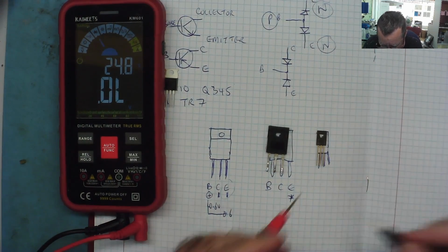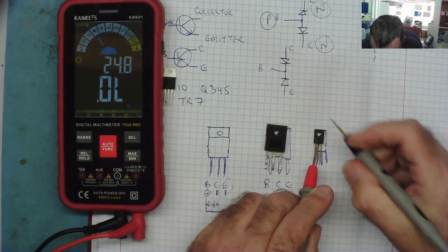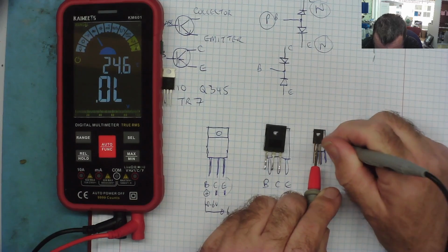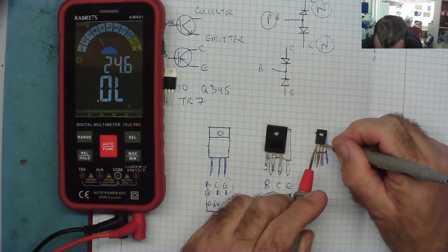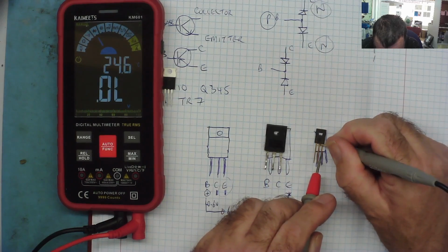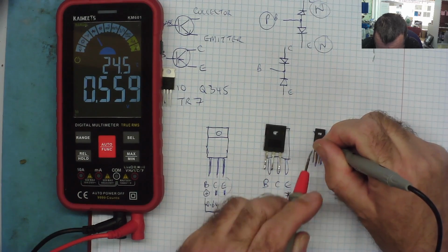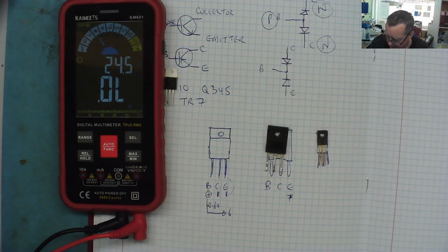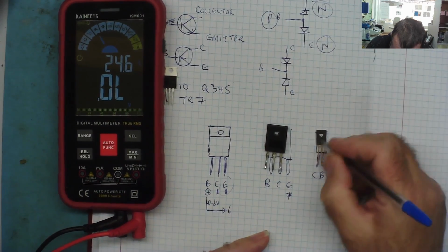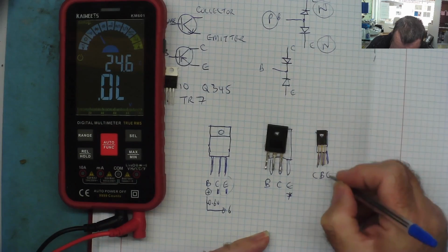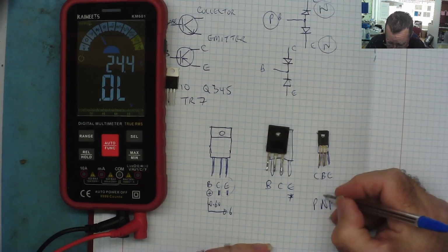that is the base in the middle and it is a PNP. That reads nothing. That reads nothing. So in that respect, you see it? Nothing to either end, black in the middle. 593, 559. So in that respect, this looks like base, collector, emitter, with a negative to the base makes a conductor. This looks like it's a PNP transistor, okay? That's how it looks to me.